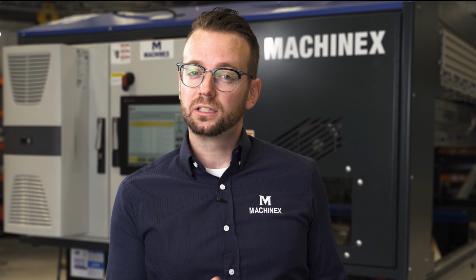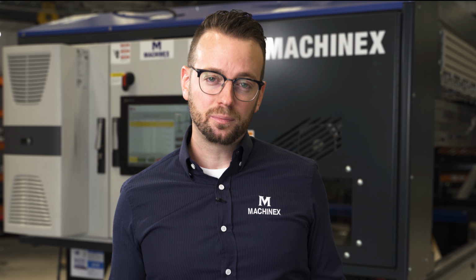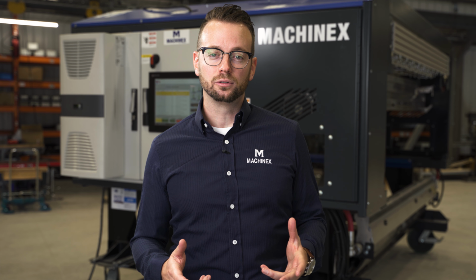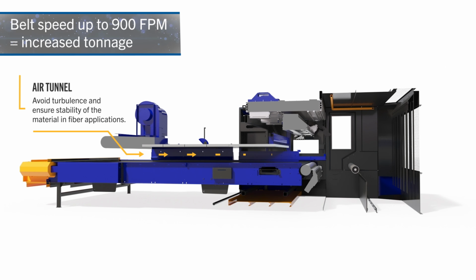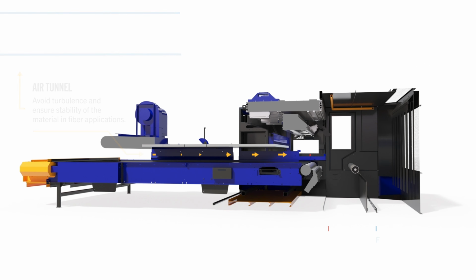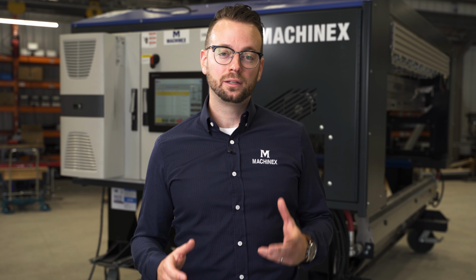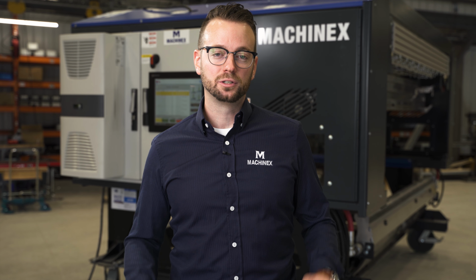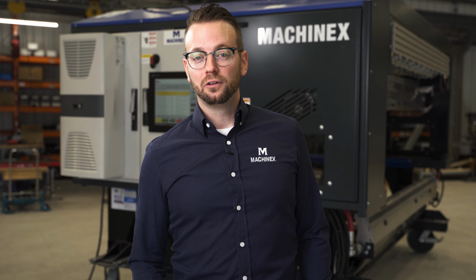On top of the different configurations that I just explained, there's a set of options that can be selected on the machine. The first option will be the provision of an air tunnel in each fiber application. The goal of this option is to match the speed of the air inside the tunnel with the speed of the belt. Matching the air in the tunnel with the speed of the belt prevents the light material from rolling on the belt, hence increasing the recovery and the purity expected from the machine. The second option will be the provision of a metal detector.